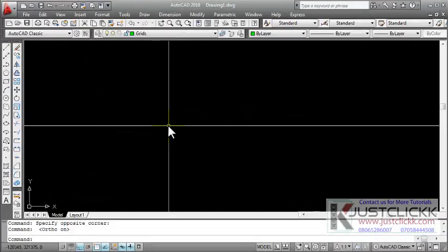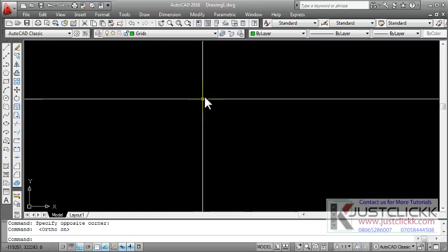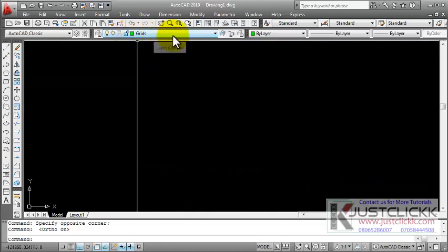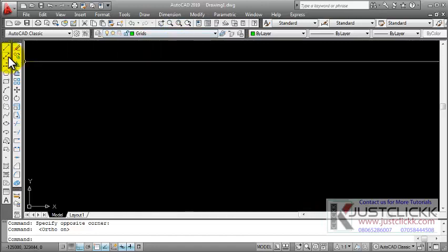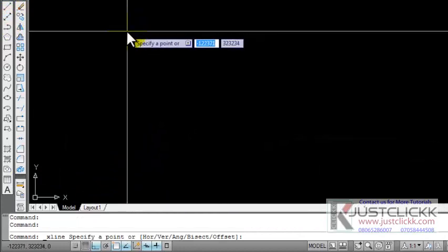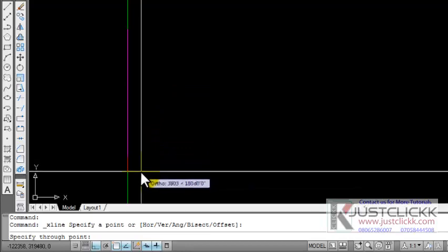Creating floor plans. To create a floor plan is something that actually starts with establishing grid lines, which is what we are going to do. To create a grid line, ensure you're on the grid layer and then pick the infinite line, which is construction line. Just click on it, specify a start point by clicking, move your cursor downward and click.